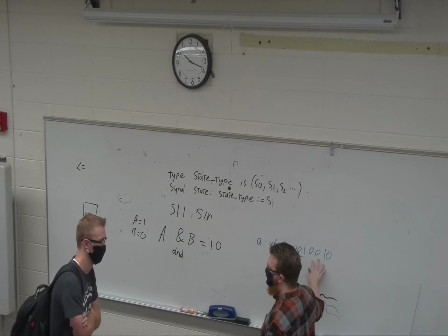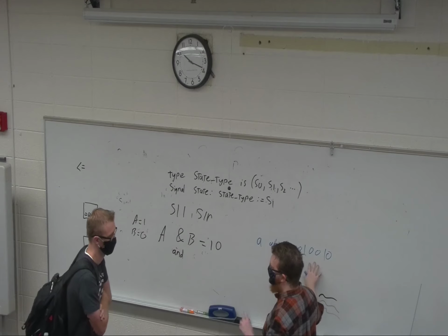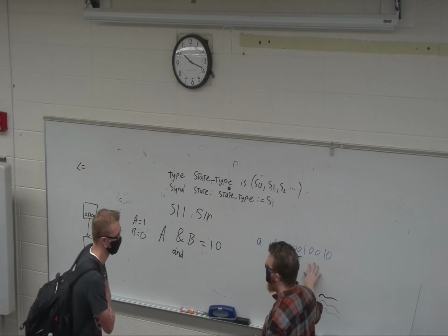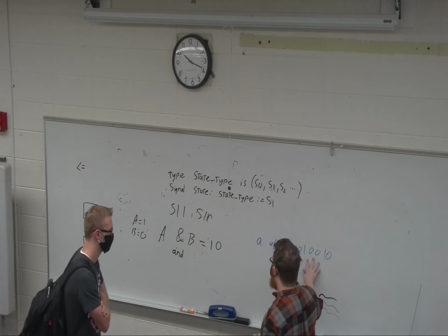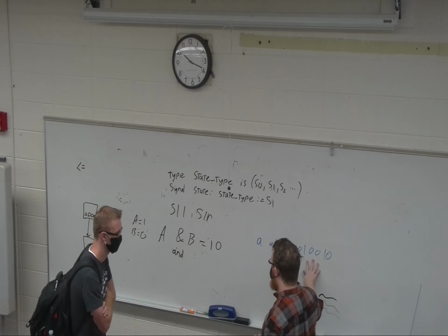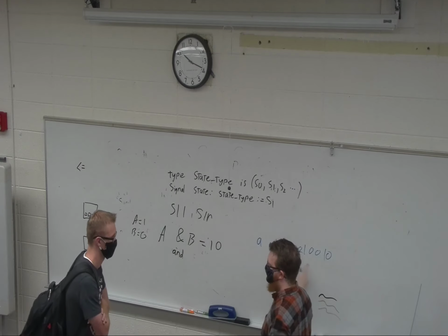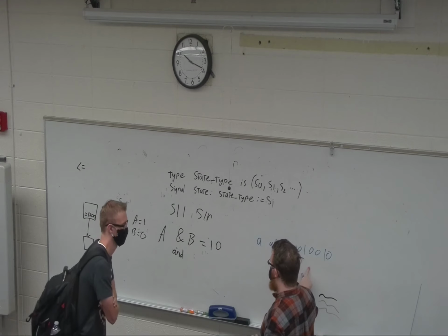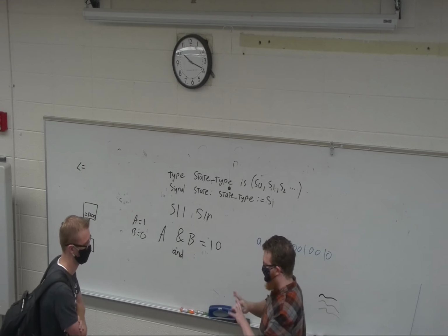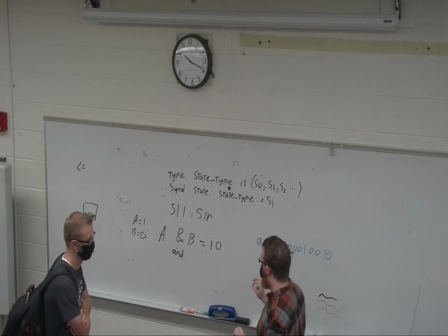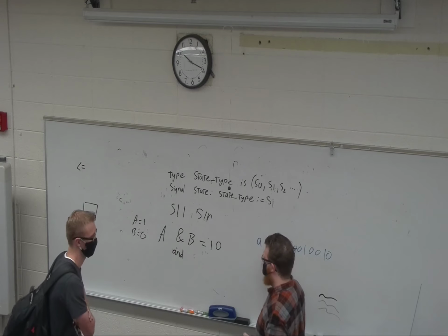In VHDL, it's more questionable whether the synthesizer is going to error or not. I know Altera more, and Altera you can configure to be okay with this. But VHDL itself, without the IDE doing something for you, is not going to be happy. VHDL does not like this because they're different types.